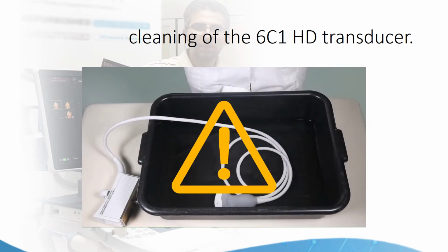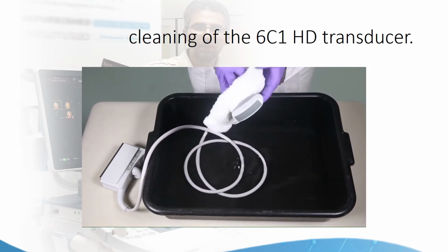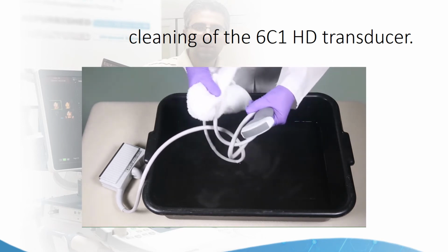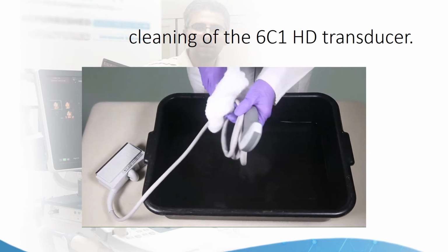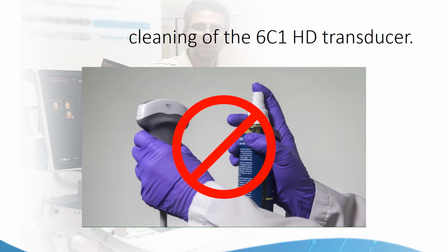Caution: leaving the transducer in the solution longer than suggested by the manufacturer may result in damage. After cleaning or disinfecting, use a clean cloth to dry the transducer and store appropriately. Do not use a spray-type disinfectant, as the pressure may force the cleaner under the lens and into the transducer casing.